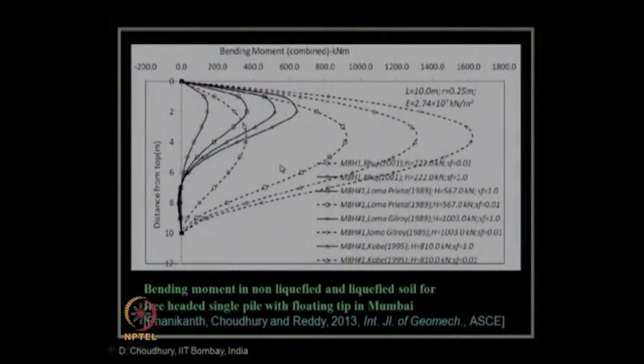So, unless we know about a site condition and from expected or earlier historical analysis or seismic hazard analysis, if you do not do this liquefaction study for a possible liquefied zone, you will end up with excessive pile bending and finally the failure like this, because of this sudden, excessive increase of the pile bending moment. Clear?